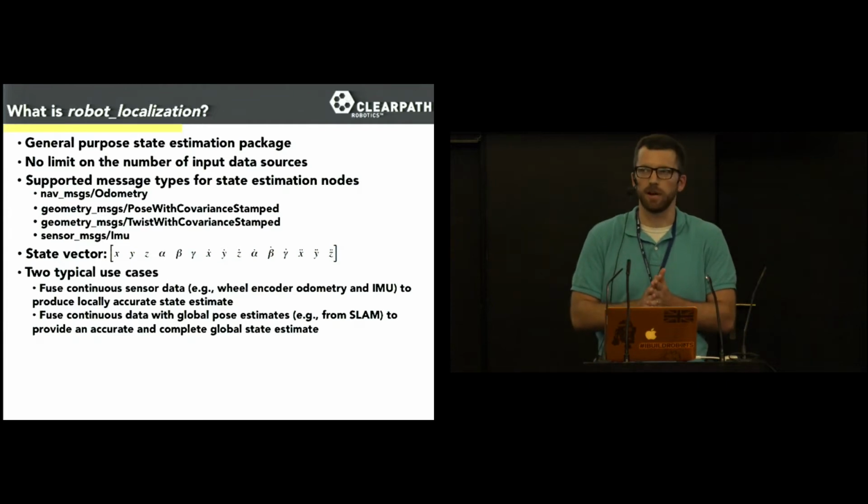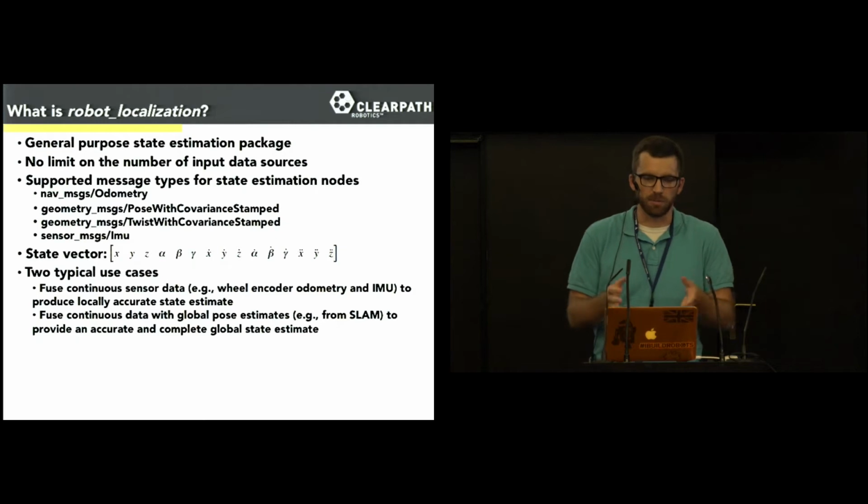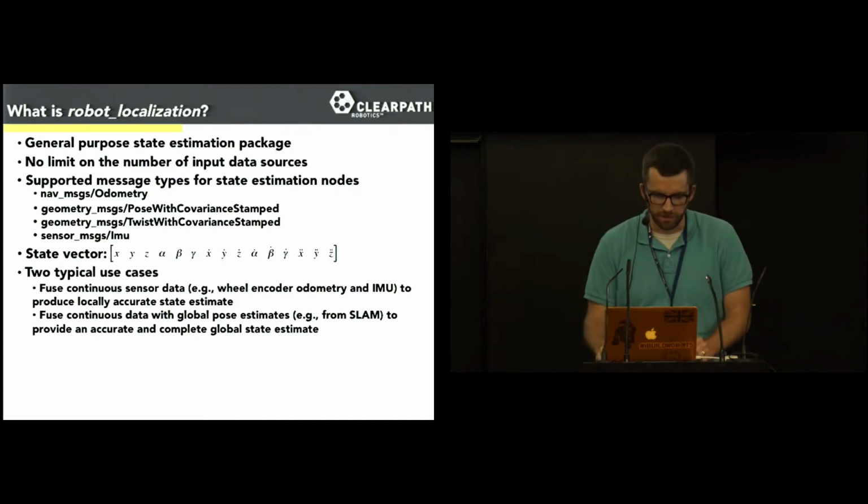And it's also good in those use cases if you have infrequent global pose estimates, like coming from a GPS at 1 hertz, and you want to make sure you have a filtered state in between those 2 readings. It's very useful.